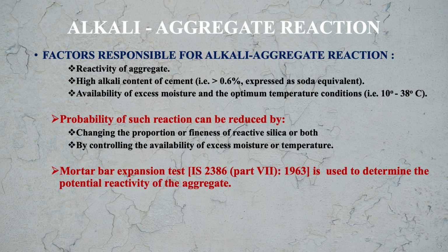The probability of such reaction can be reduced by changing the proportion or fineness of reactive silica or both, or by controlling the availability of excess moisture or temperature.